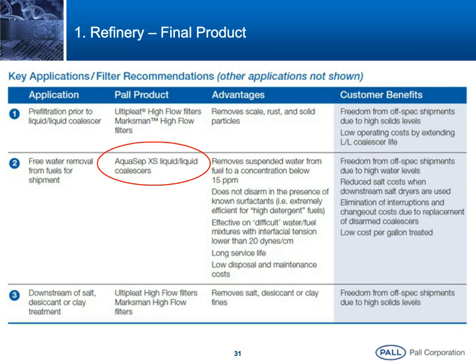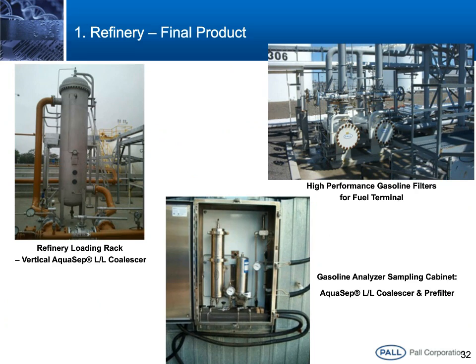Here we can have a few installations, a vertical coalescer on the left-hand side, horizontal on the top right, and a very small filter in the bottom center. This is actually a small analyzer filter, making sure that the analyzer achieved efficient protection from particulate and water contamination.